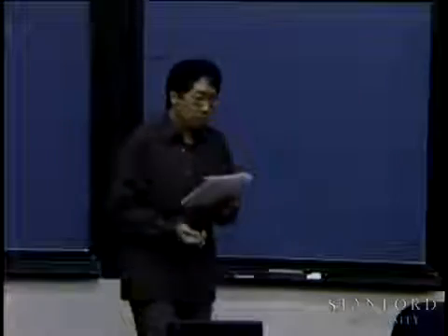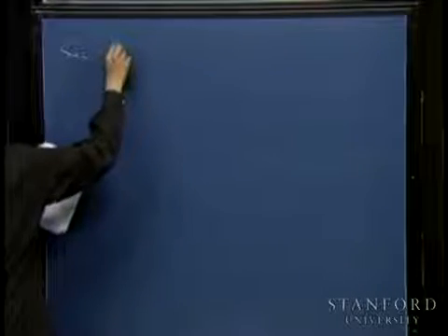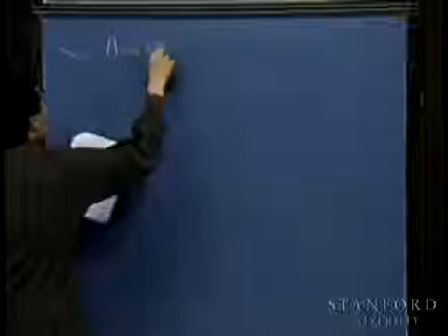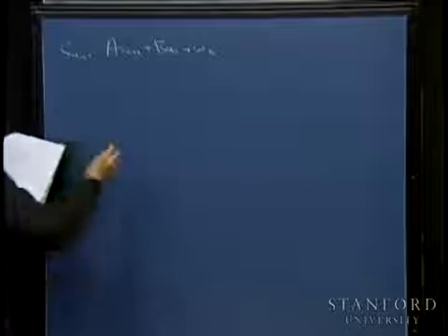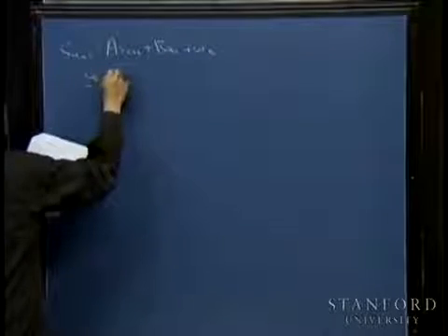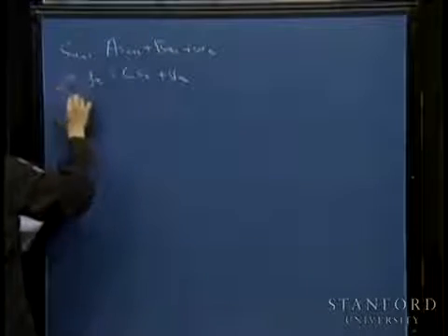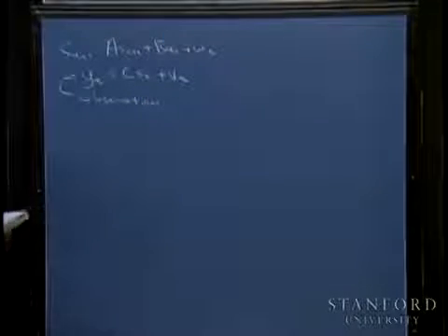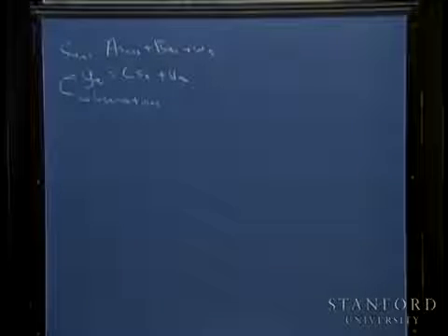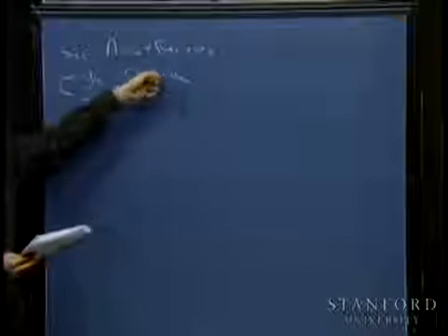You recall from the last lecture, I started to talk about one specific example of a POMDP, which was this linear dynamical system. This is the LQR, linear quadratic regulation problem. But I changed it and said, what if we only have observations y_t, and what if we couldn't observe the state of the system directly, but had to choose an action only based on some noisy observations that may be some function of the state.